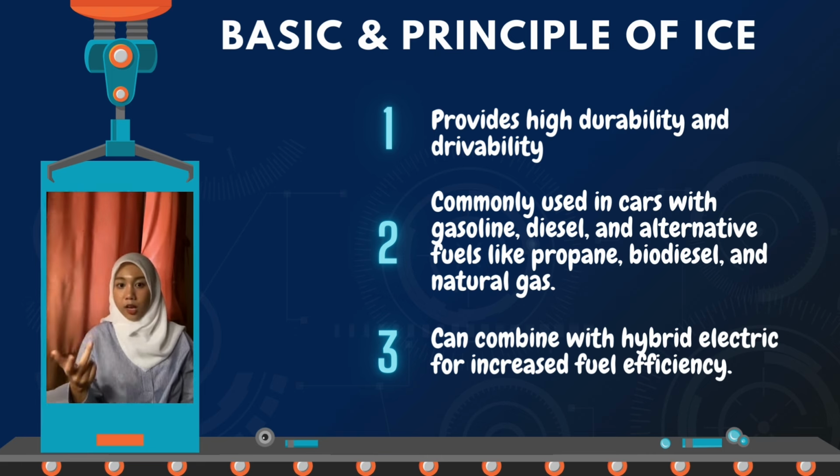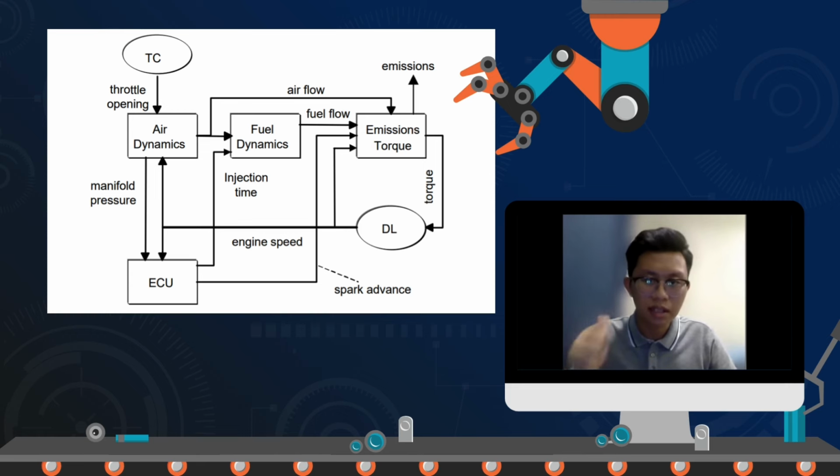In the figure given, a diagram of an engine dynamic is shown. The main parts consist of the main physical important submodules such as the engine control unit and the in-cylinder process. There are two dynamic subsystems that make up the intake manifold block, while the fuel dynamic model depicts the effect of fuel wall wetting and evaporation in order to estimate the real port air-fuel ratio, which substantially influences engine torque and emissions. The air dynamic model computes the airflow rate through the throttle body and the engine port.